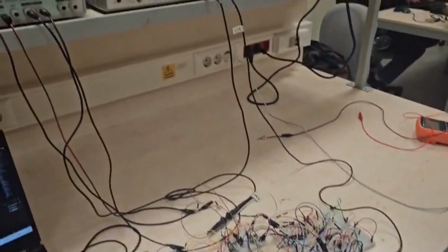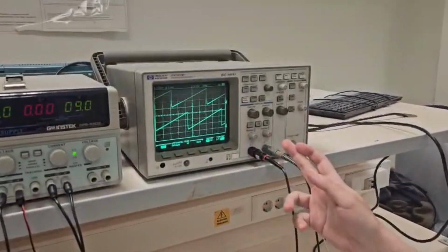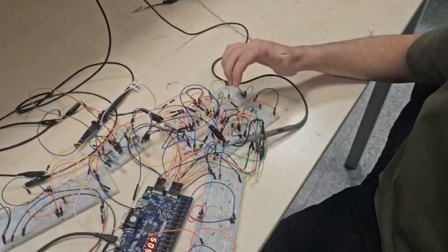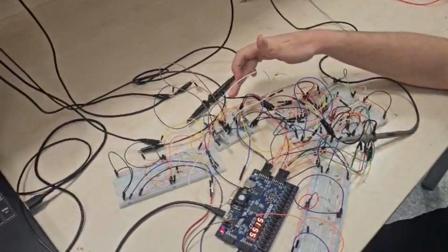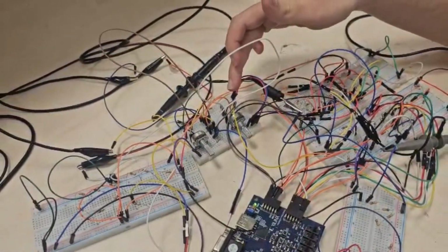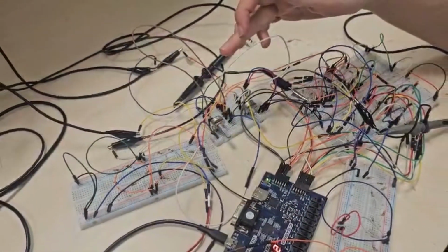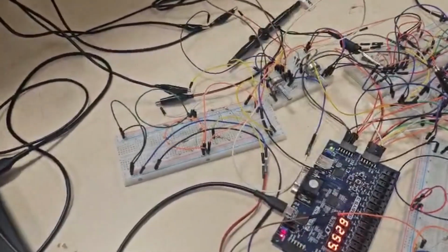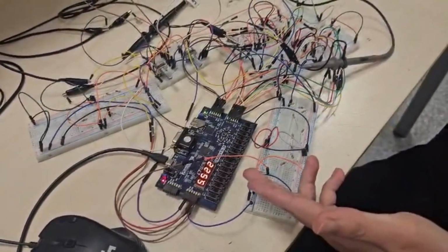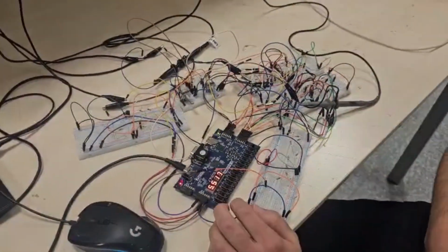So the way my project works is that we calculate 256 points in the waveform that we want, and then we send those points digitally from Basys to the digital to analog converter circuits here. Then the output signal goes into a low pass filter where it's cleared from noise. Then we have a non-inverting amplifier circuit with potentiometer so that we can control the voltage. Then that gives us our output signal, but we also put it through a voltage divider and then into the JXADC port of Basys so that we can see the voltage while we are adjusting it through the 7-segment display.